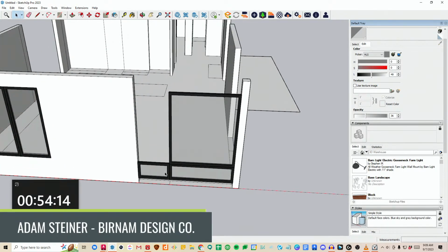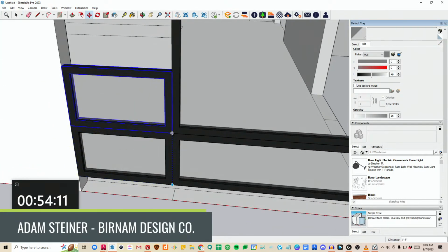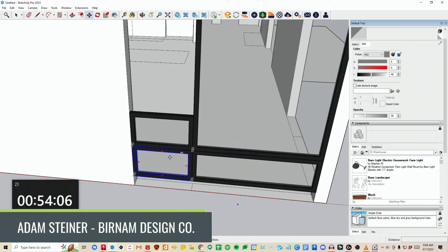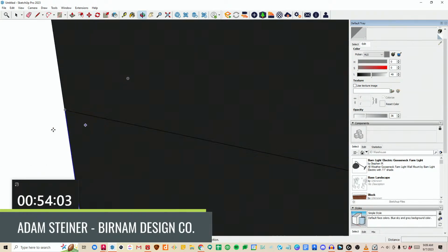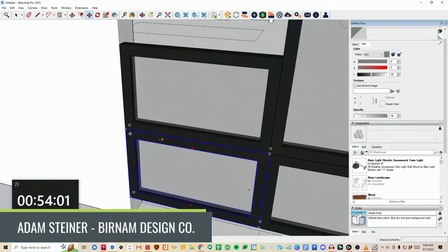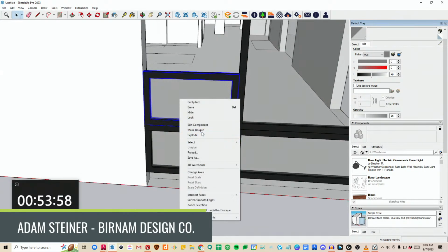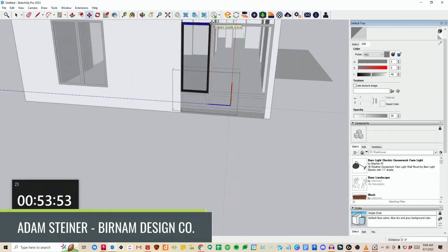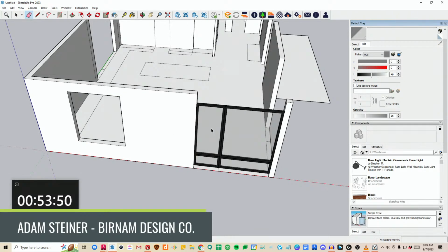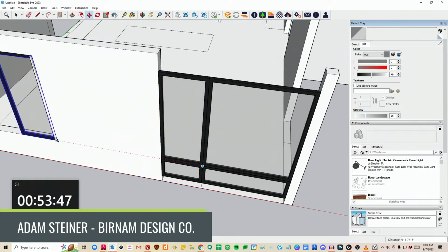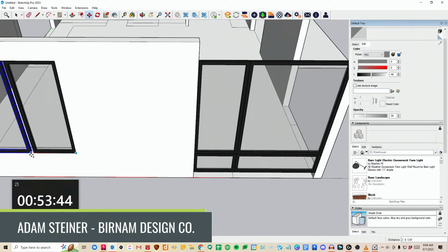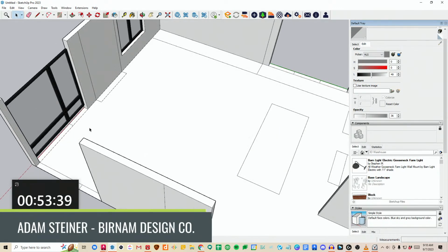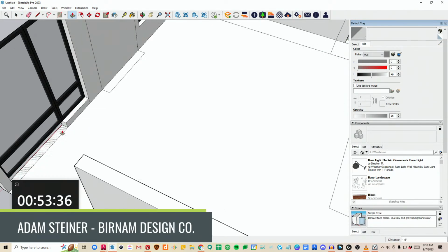I'm going to delete this window. Copy this up. Are all these out of square? Or is just that one? Okay. So SketchUp can be really finicky, and if you have something like that that's out of square or off, it can really throw off your model and be very annoying to fix later. So I'm going to make a new one based on our old one. And then hopefully this is now coplanar and all that. Okay. That's probably better.